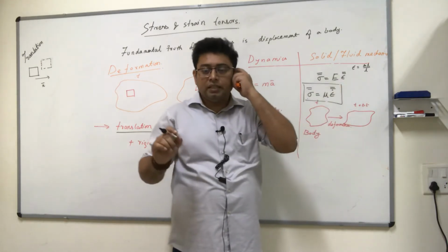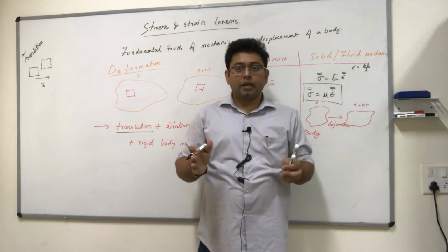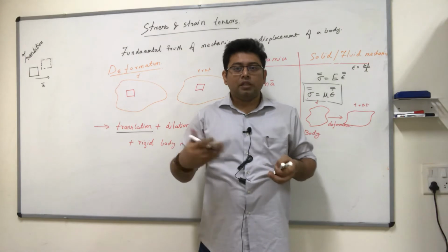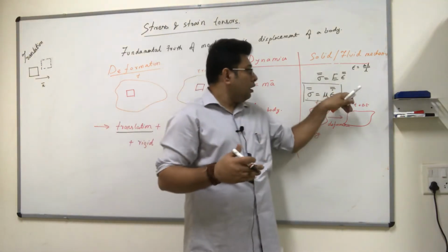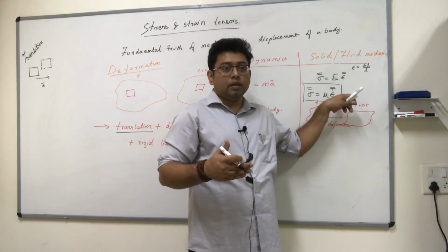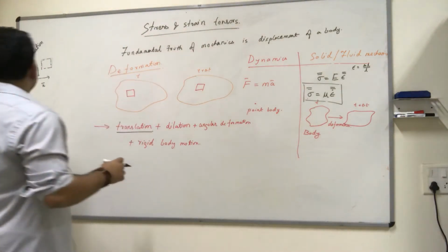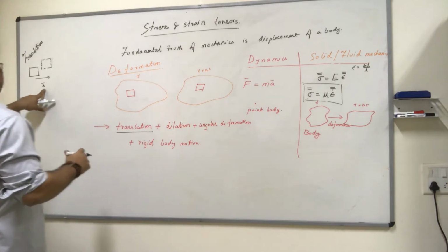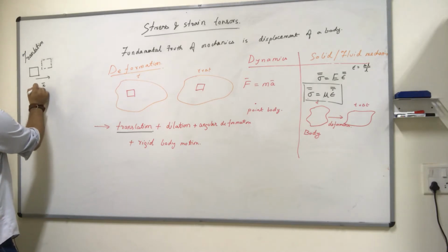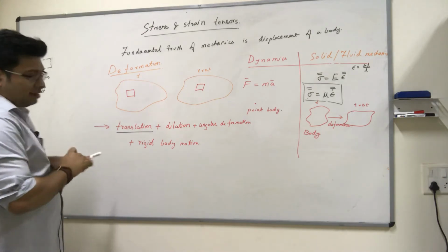And this is fundamentally connected to also the control volume approach that we take, and I'd like you to think more about it. Just give it some thought. This is not a very trivial thing, but there is a reason why strain rates and control volumes sort of go together sometimes. So here we have x hat, which is the displacement, but we are going to be worried about the velocity. So for translation, things are rather straightforward.